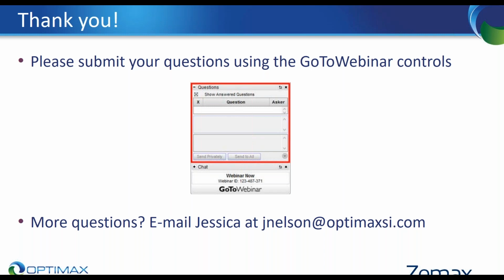So the references. Yeah, so that is something we do use a lot of times. So the transmission spheres and the individual elements are characterized interferometrically as well. But then we also do tests of the system as well. So there are interferometric measurements. The other thing that we also like to make sure that we at least do here at Optimax is that we have multiple different measurement methods to characterize the same surface, so that we can test and calibrate one to another to make sure that we minimize the measurement error.